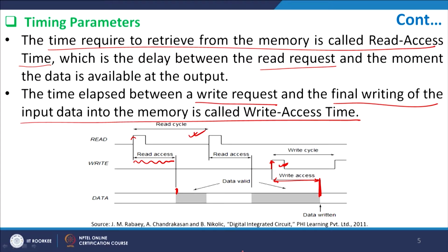The idea is to make the read and write cycles closer to each other, which means the frequency of operation will increase, and you should be able to do that. But the problem is you cannot reduce the read and write cycle beyond a particular limit, the reason being there will always be interconnect delays and so on, which restrict the high frequency operation of the memory. So, we have understood the basic timing, and we have also understood the basic concept of the size of a memory.